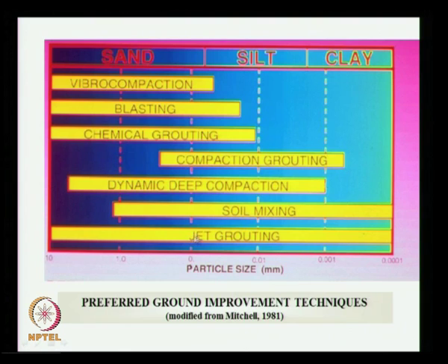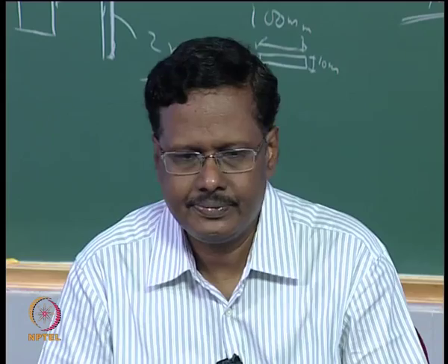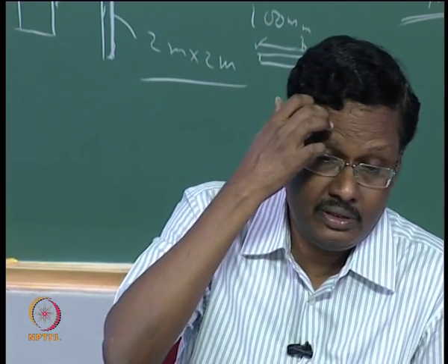One of the advantages of jet grouting is it can be used for any type of soil, whereas vibro-compaction and blasting can be used only for sandy soil, they cannot be used for clayey soil, and soil mixing is not possible for certain dense sand deposits. Okay, we will see tomorrow in our department.